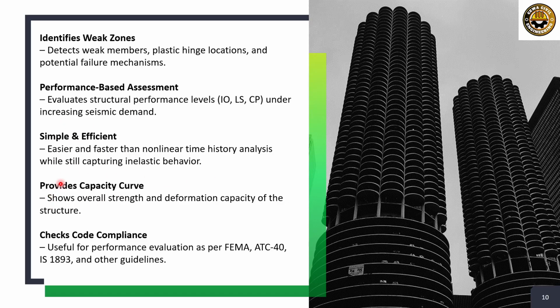One more thing, it provides a capacity curve. We discussed earlier what a capacity curve is. It shows the overall strength and deformation capacity of the structure. Pushover analysis also checks code compliance. It is useful for performance evaluation as per FEMA, ATC 40, IS 1893, and other guidelines.